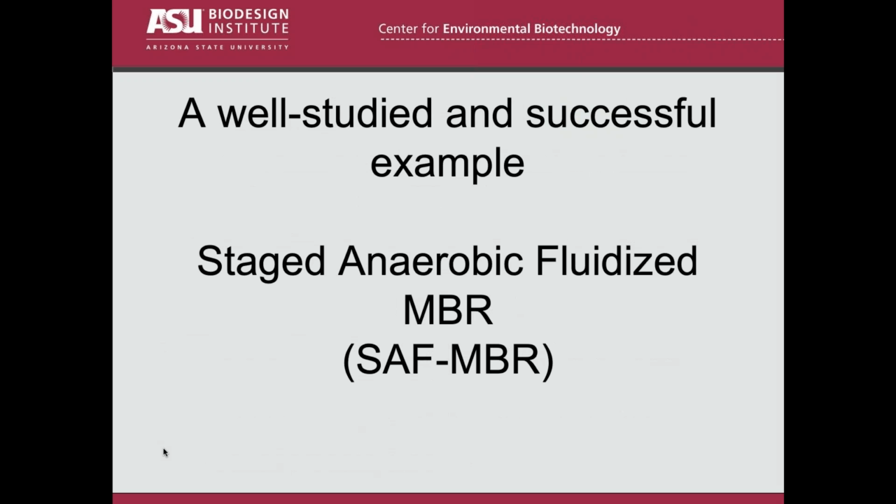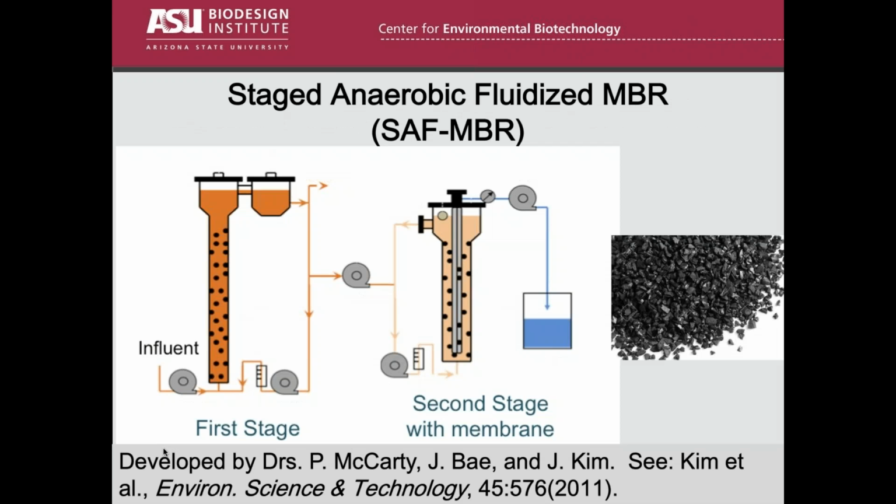Now, I'm going to talk about one particular example, one that's been very well studied. We have some data on it. It's called the staged anaerobic fluidized MBR, or SAF-MBR. And here's a schematic of it. You already saw this earlier from Andrew's talk. And so this is a two-stage system here. It was developed jointly by Professors McCarty and Jeho Bae. And they've done really quite thorough testing of this in a number of countries around the world.